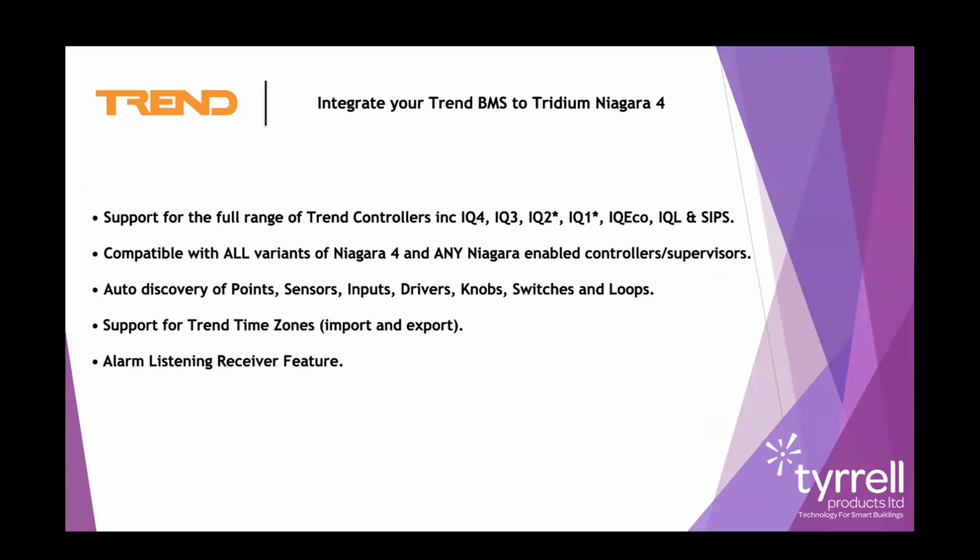The next driver we have, which is one of the first that we developed due to high demand from our clients, is our trend driver. So you can integrate legacy trend controllers and legacy trend systems such as 963 into Niagara. So it's compatible with all variants of Niagara 4 and any Niagara-enabled controller. That may be a controller we manufactured or the likes of LinkSpring, Honeywell, or a native Niagara Jace controller.